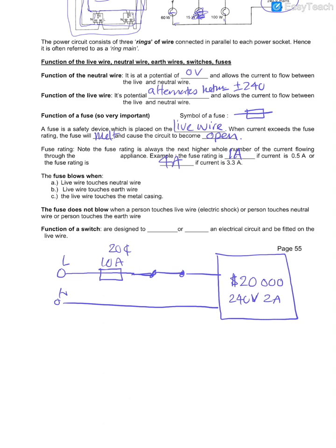The only problem comes when what? When suddenly some fault develops, suddenly let's say 9 amperes come. Will the fuse melt? No. It will go straight through, the fuse will say, go through me, no problem. You come here and then what happens? You will explode. You will blow. So the computer has managed to protect the fuse. Right, the $20,000 computer protects the 20-cent fuse, the other way around. So you cannot have a fuse that's too high.